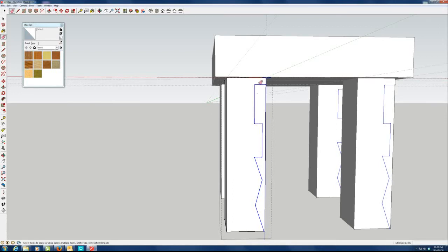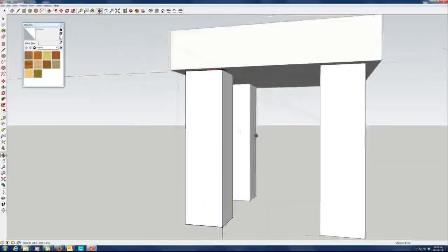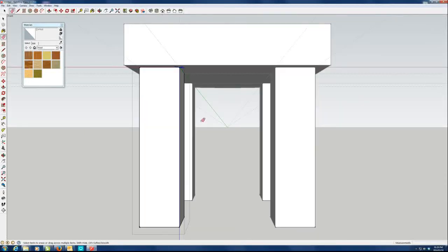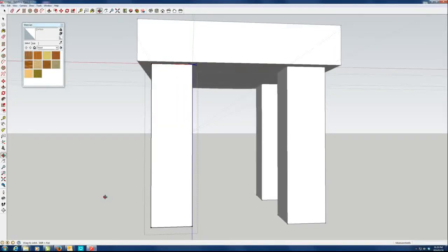You can also use curves if you wish to draw this. I'm going to use curves just to show you. Again I'm going to view the front view, and I'm going to draw the profile. Remember the rules we spoke about last time. So I'm going to start on the top edge, on the right hand edge. Draw an arc. Again, draw another arc.